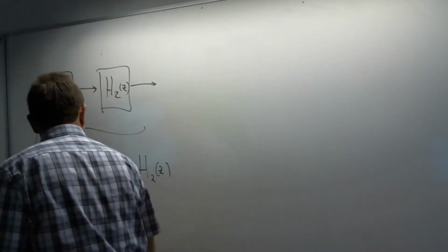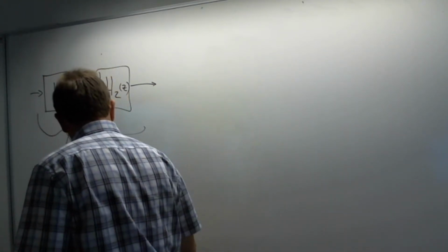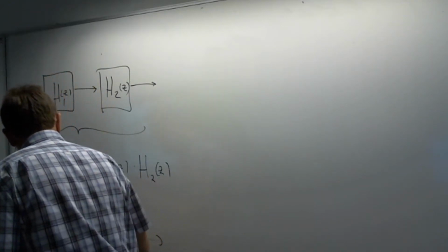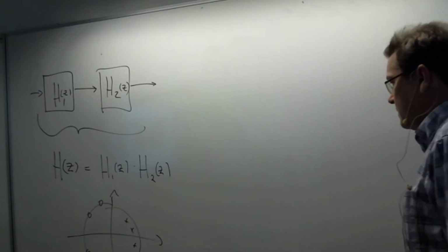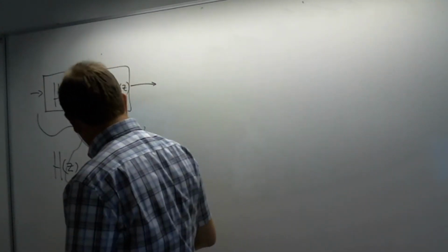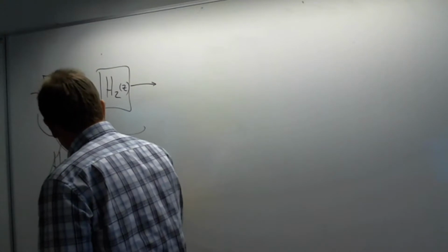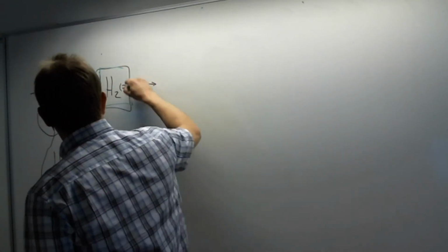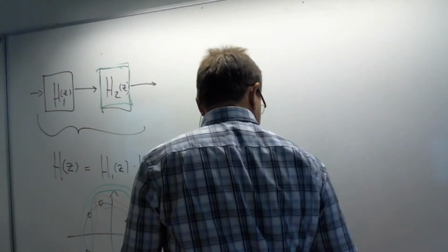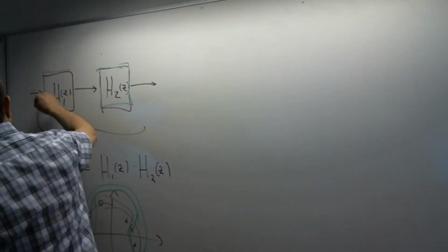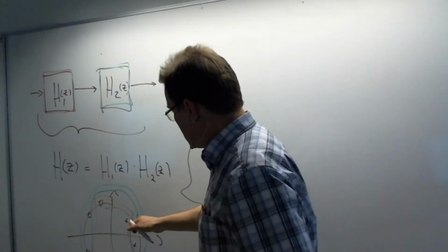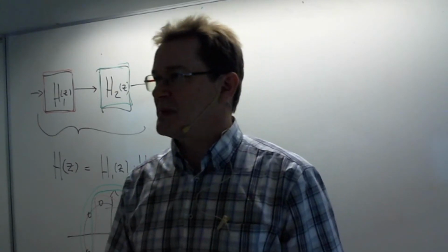This is used the other way around in reality. Any system, if you think of the zero-pole plane, if you have multiple poles and zeros, you get better calculation accuracy if you start partitioning the system. Take those zeros and poles in one system and then take these to the other system. Basically you have two second order systems, so that's second order system division.